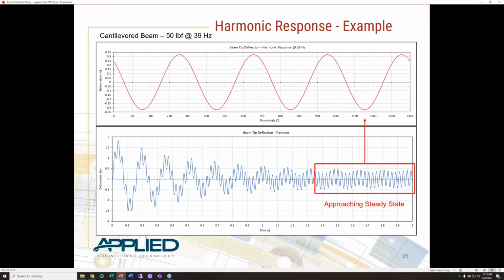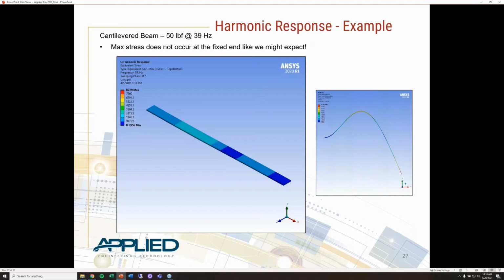We're going to move on to the stress strain output from the harmonic response. And so here is again the stress strain output from that harmonic response load. So here's a steady state response of that beam under that load. This is kind of a combination of mode 1 and mode 2 that we're seeing here. But we are getting some significant influence from mode 2. You can kind of see that inflection point 3/4 of the way down the beam.